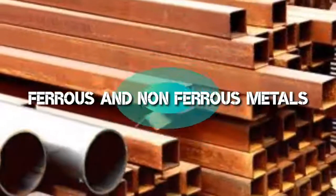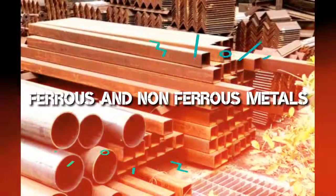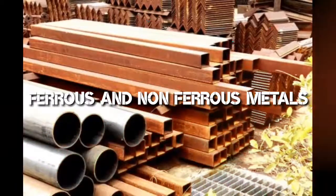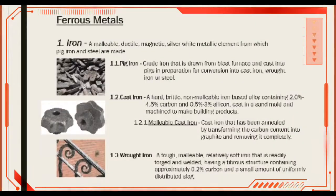A ferrous metal is a metal containing iron as a principal element, while non-ferrous metal is any metal containing little or no iron. Now let's talk about ferrous metal. Iron is a ferrous metal. Pig iron is crude iron that is drawn from a blast furnace and cast into pigs in preparation. Under cast iron is malleable cast iron, cast iron that has been annealed by transforming the carbon content into graphite and removing it completely.